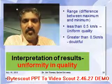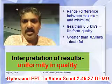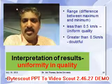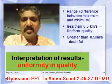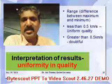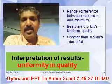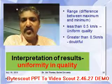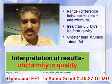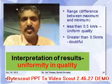And how the uniformity in quality is assessed is given in this slide. The range, or the difference between the maximum and minimum magnitude of apparent velocity, is considered. If it is less than 0.5 km per second, then it is said to be of uniform quality, and if it is greater than 0.5 km per second, it is said to be under a doubtful condition. There also more tests need to be conducted.